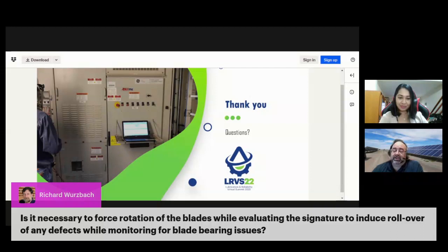The question comes in depends on the wind. So if I have 3 to 2 meters per second, which is where a majority of towers will do what's called cut in, they'll start. I'll detect the problems, but I have to look at all the signatures and I have to look at a bunch of noise because the controls are dumping what's called VAR correction in to correct for power factor and other electrical conditions and to stabilize the grid. It isn't until we get up to about 5 to 8 meters per second that things begin to stabilize, and usually over 10 meters per second wind, so a little over 20 miles per hour, for us to have full power coming off of a turbine.